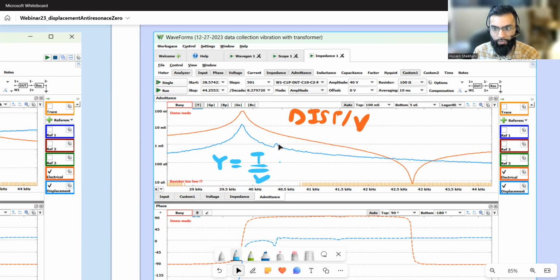And this little peak here is actually a real phenomenon. This often happens in ultrasonic transducers where you get different small peaks or different occurrences around the resonant frequency or even the anti-resonant frequency. But here, we see no specific trend. Everything here is normalized, so it's not like your experiment was wrong. These are ratios. Displacement doesn't even notice that there's an anti-resonance frequency there. So that's interesting: displacement does not even see the electrical anti-resonance at all.